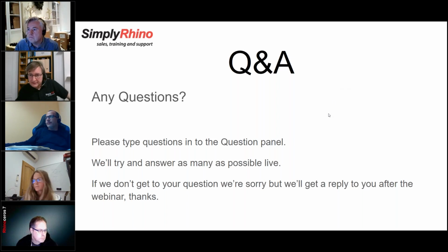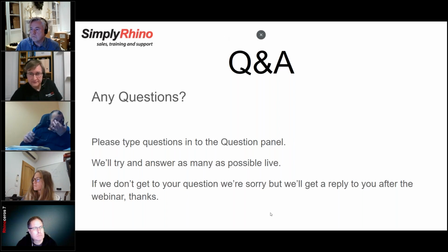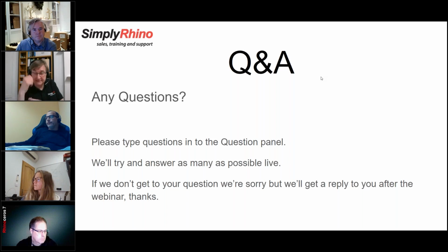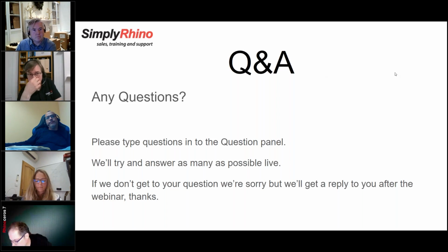Okay, one more here, which I think Vanessa has answered in the chat panel, but I just thought I'd read this out because it's an interesting question. The question is from Ramsey: is there any way to make the corners of sub-D surfaces sharp instead of rounded as the default? And yes, what you need to do is just pick the corner vertices, or the corner vertex if there's only one, and use add crease, and then you'll get the sharp corner.